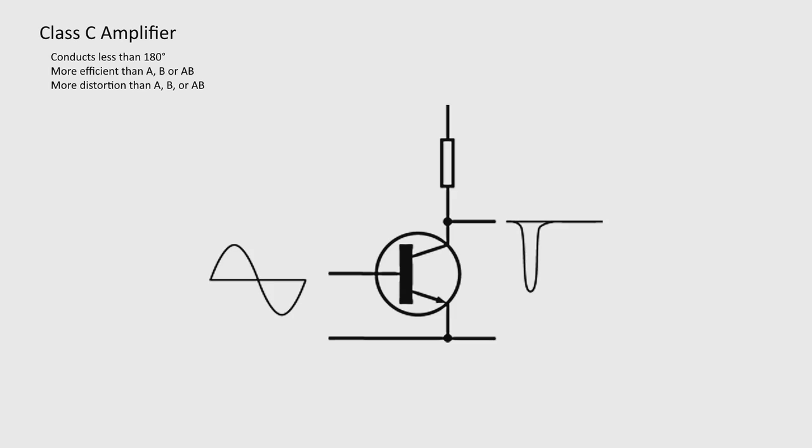You put a sine wave signal in on the right-hand side, and on the output you've only got half the waveform. It's not even as wide as half the waveform. You see how it's kind of sloughed off there? It does come down to a peak or a dip at the same point on the curve. Distortion-wise, you're going to hear this.